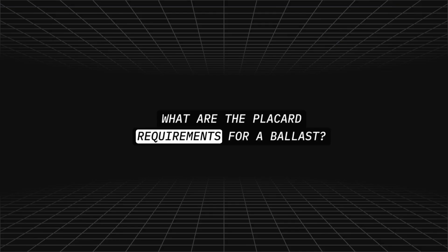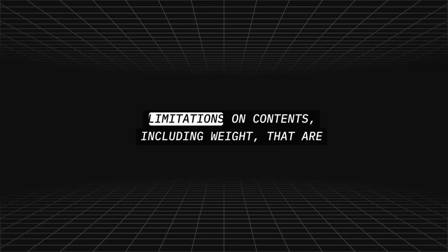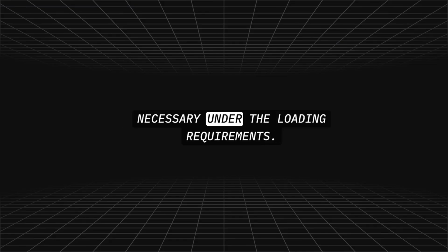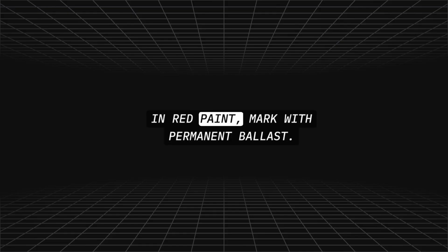What are the placard requirements for a ballast? The ballast location must have a placard stating any limitations on contents, including weight, that are necessary under the loading requirements. What is recommended for marking of permanent ballast? In red paint, mark with "permanent ballast, do not remove."